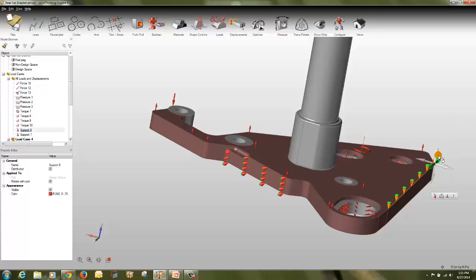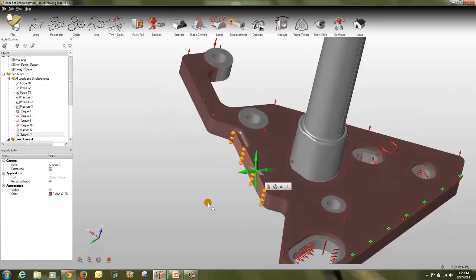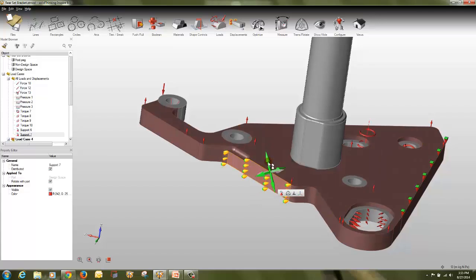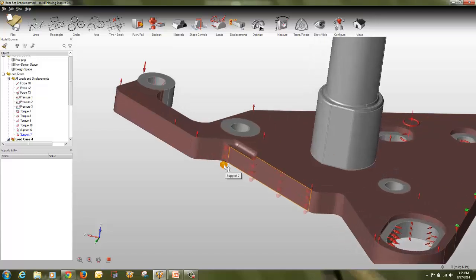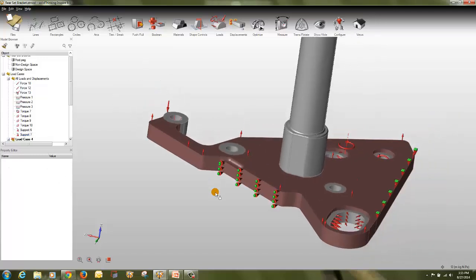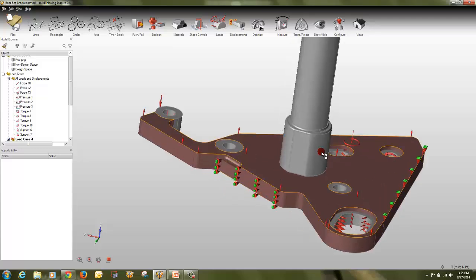So this is showing the global axis, Z, X, Y. So I am constrained to Y. Here I have constrained to Y and Z. So in this way you can put the constraints on whatever axis. If you make it all green, it's of no use, it will be like invisible. So you have to make sure that any one is active. So in this way you can find that with one axis active, two axes are constrained. So in this way you can apply the constraint to